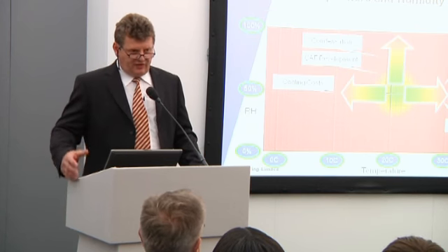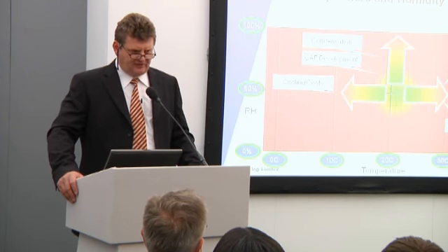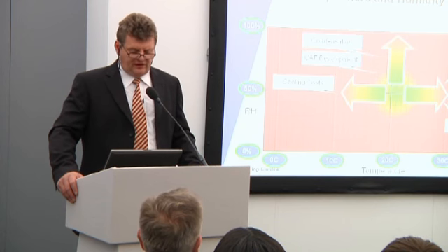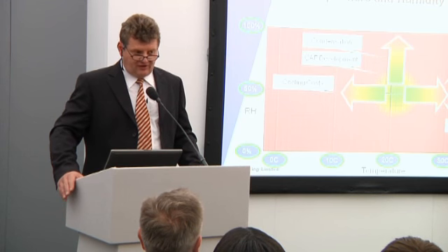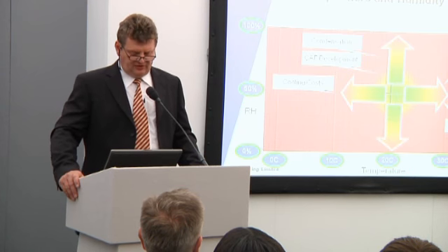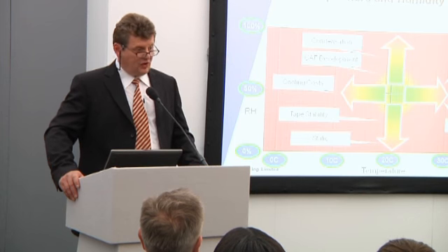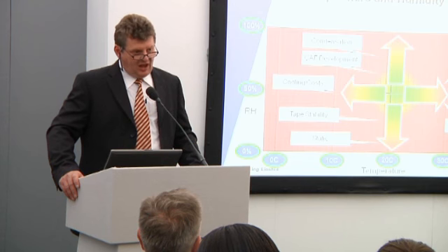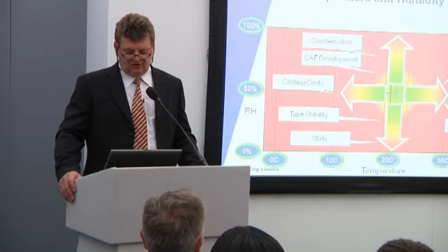With printed circuit boards, there is also an issue of a thing called CAF development, which is a filament development which can grow on printed circuit boards and can cause failures. But that only happens at high temperatures and very high humidities. Low humidities are associated with tape stability, the old paper tapes and paper card systems. And low humidities have also been associated with a thing called ESD, electrostatic discharge.